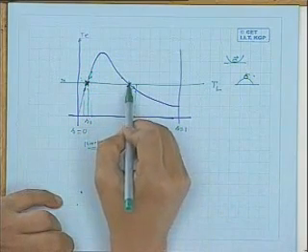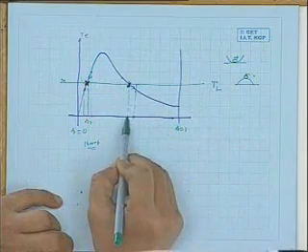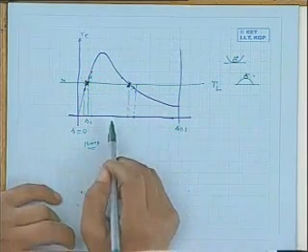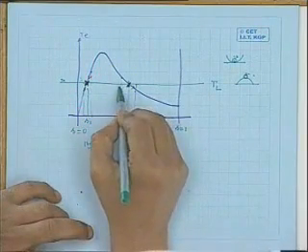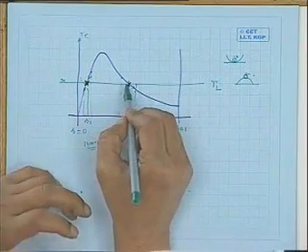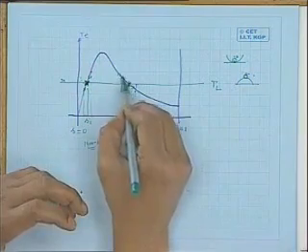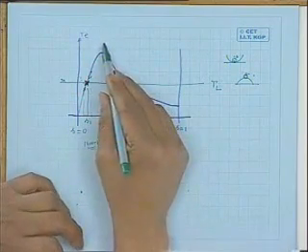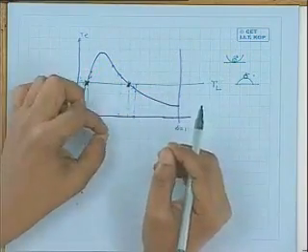That is slip 1. Similar is the case if you imagine here. This is the initial operating point. So a slight increase in speed in this direction because of some disturbance, we find the electromagnetic torque becomes greater than the load torque. The machine further gets accelerated and the operating point goes away from it.